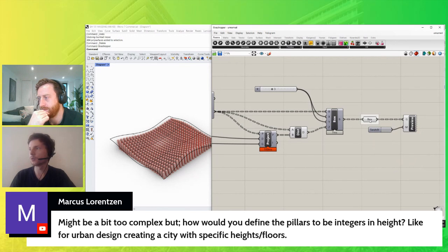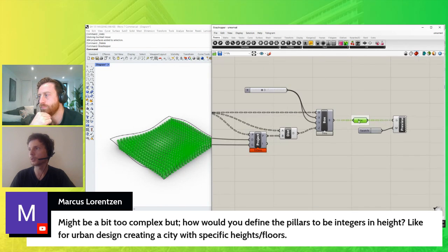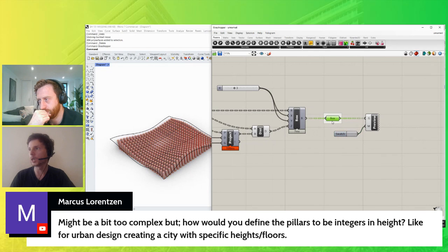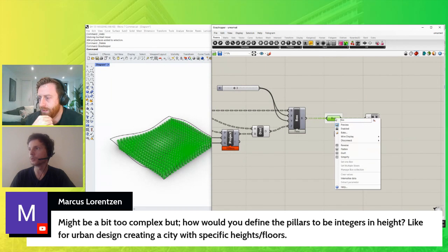There is no standard. One other thing I like to do is create little intermediate containers. These don't do anything, but it's a stopping point of like, okay, I created all my boxes, I put them here, I highlight them by doing a little group around. Again, we'll touch on that in Grasshopper 102. And you can even rename that and say, these are my sculpture boxes.